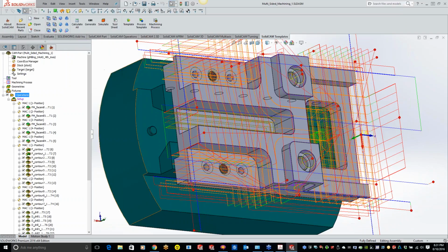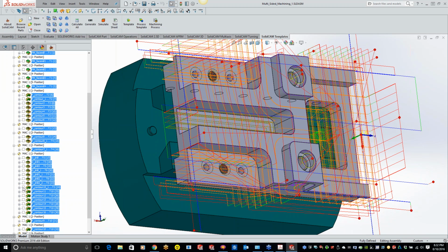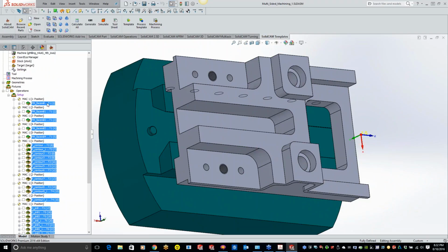So Kevin, this is one that a lot of my customers ask as well. If you're going from operation to operation, say you're programming a pocket, and then you've got a drill cycle, or a contour, whatever it may be, is it possible to put an M0 program stop while you're still programming, instead of having to put it manually in the G code? Oh, absolutely. Yep, that's a real nice feature.